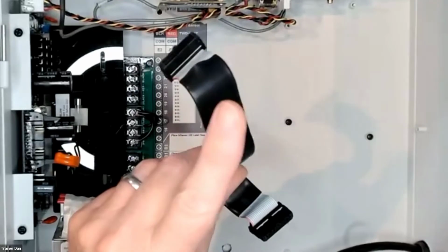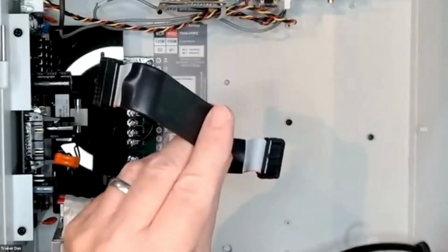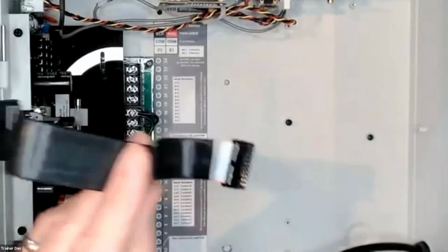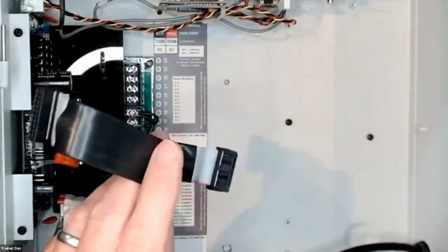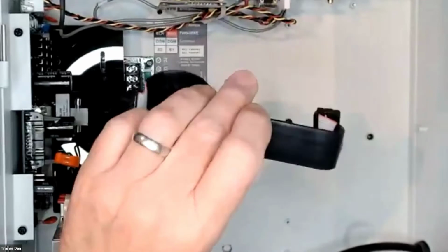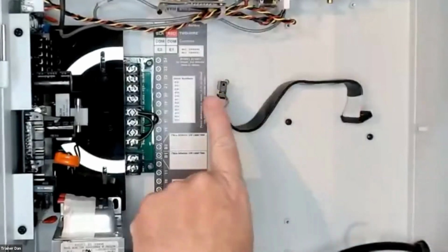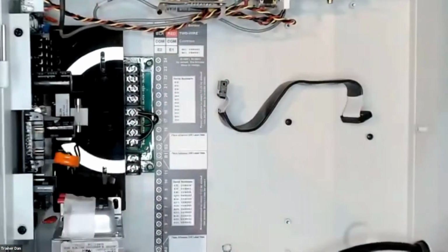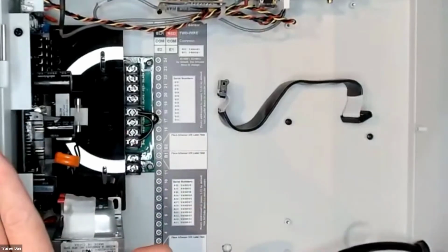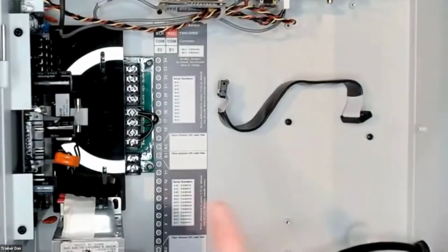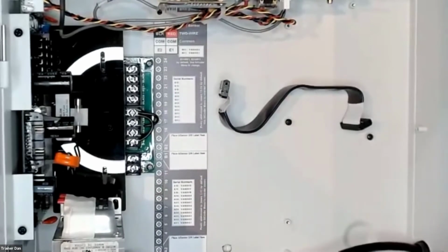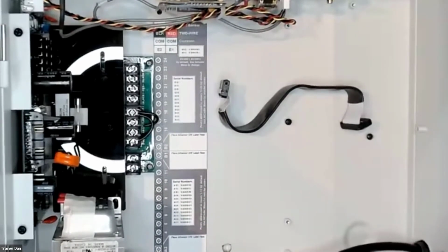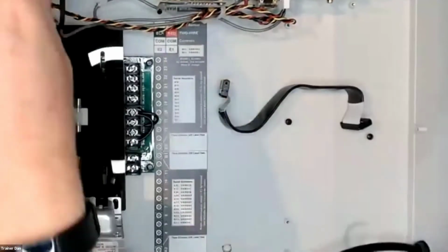If you disconnect the ribbon cable from the display on the panel while powered, very likely you're going to brick it, and that isn't a warranty issue. So if you have to remove this panel, which I did for access, power it down and then remove it, because you're going to need to remove the ribbon cable. Excellent point. Sorry, didn't mean to derail you. No, it's spot on. That's perfect.